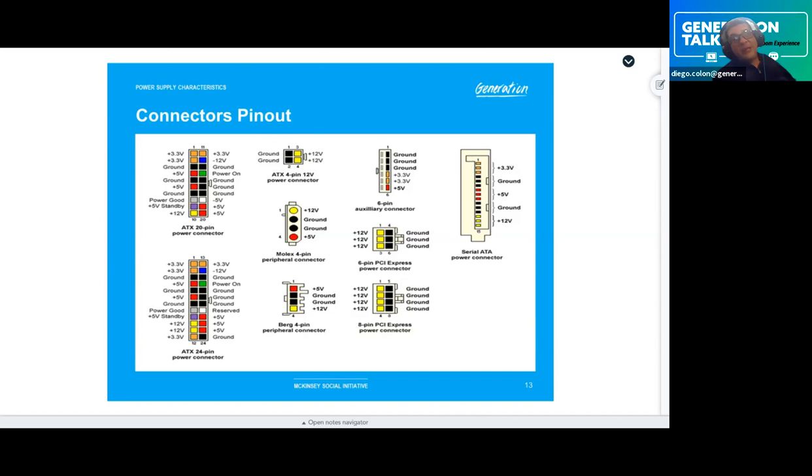The 24-pin connector looks identical to the actual 20-pin connector. The only variance will come towards the bottom. You'll notice that on the ending here, we had the purple, red, yellow, red, purple, red, yellow, red. Obviously, these are the last 4 on the end, which is your extra 12 volts, 5 volts, 3 volts, and ground coming in.